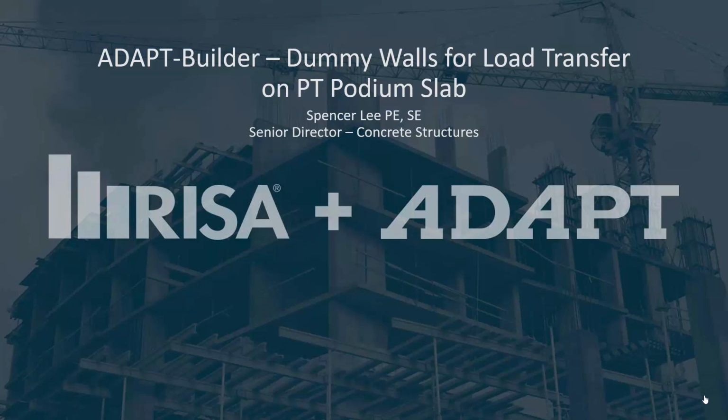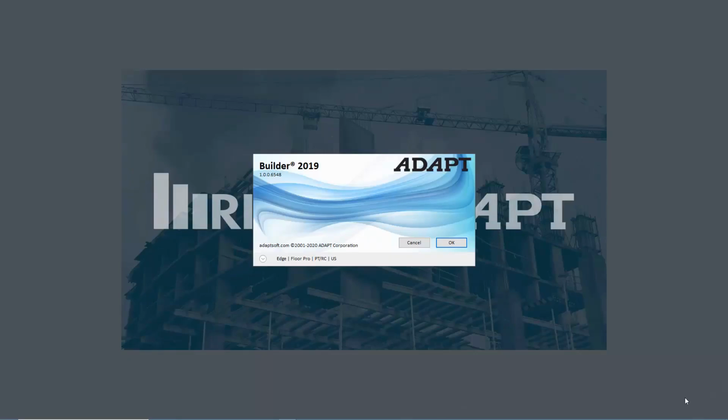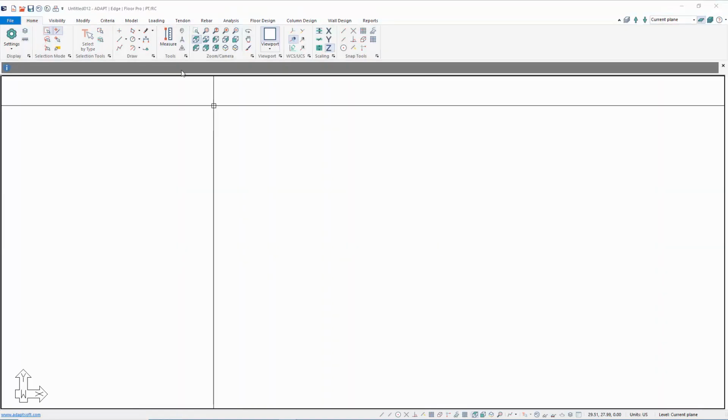In this video tutorial, we're going to discuss how to create dummy walls for load transfer of one-way slabs onto a podium slab in Adapt Builder. In this tutorial, we're going to be using Builder 2019. We're going to have Edge and Floor Pro enabled, and then we would also want to have PTRC enabled in order to develop post-tensioning on the podium.